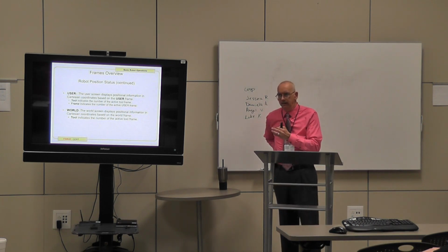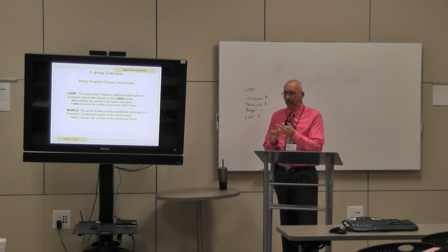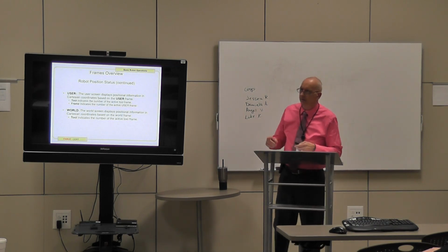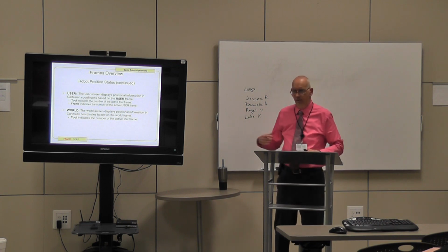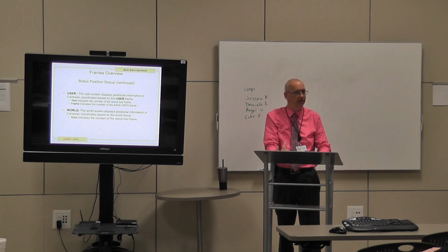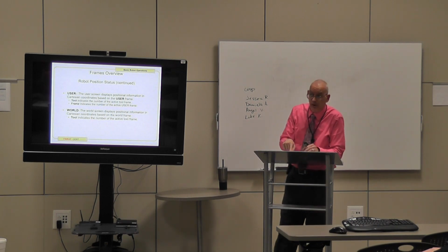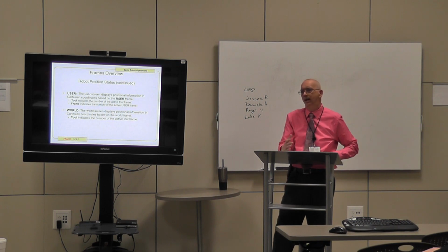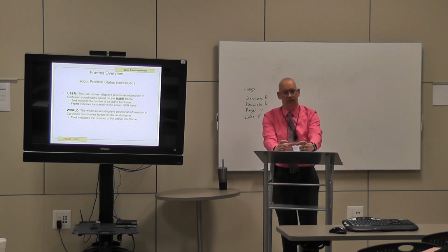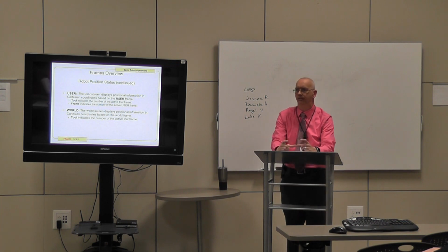Behind the robot. Okay? So that's where our 0 is. And we move outward this many millimeters. We move side to side this many millimeters, or up and down this many millimeters. When we're in user, we have defined that frame already. So what we're doing now is we're taking it off of that point of origin that we defined in our user frame. And so when we read that positional data, we're reading it according to what our user frame is.